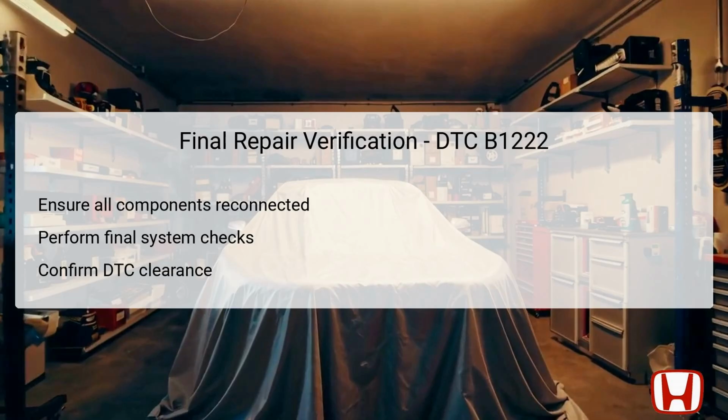This may involve running the climate control through its various settings to ensure proper airflow and temperature regulation. Additionally, using the Honda Diagnostic System, HDS, to confirm that the DTCs have been cleared and do not reappear is essential. This step ensures not only that the repairs were successful, but also that the vehicle's systems are aligned for optimal performance moving forward.